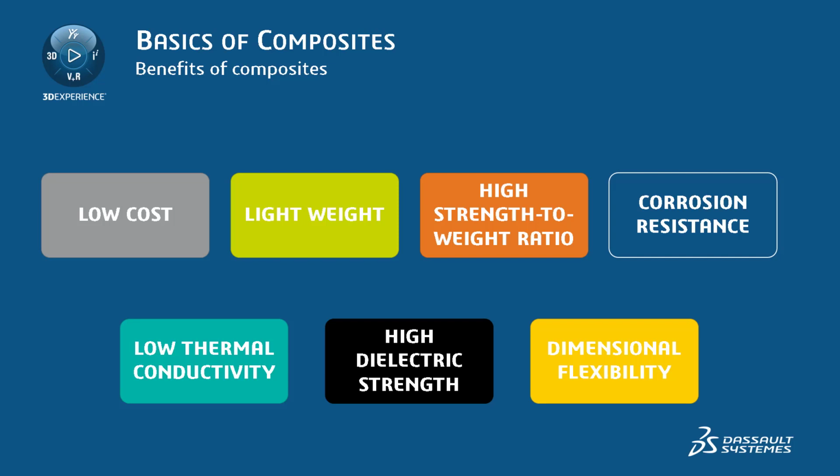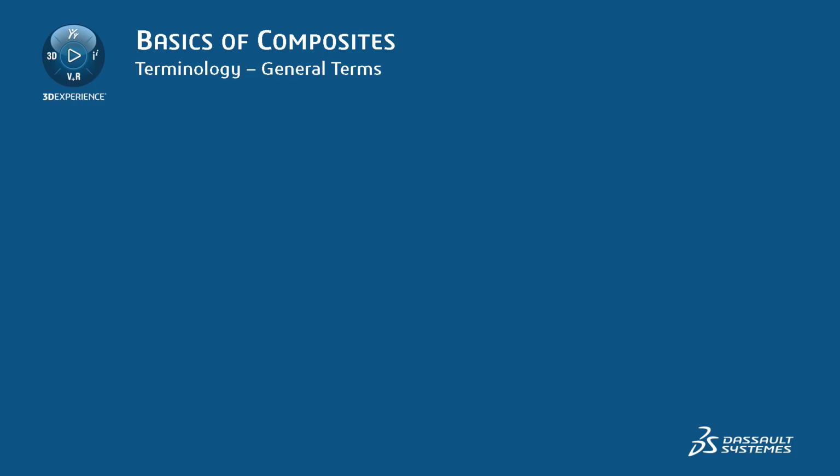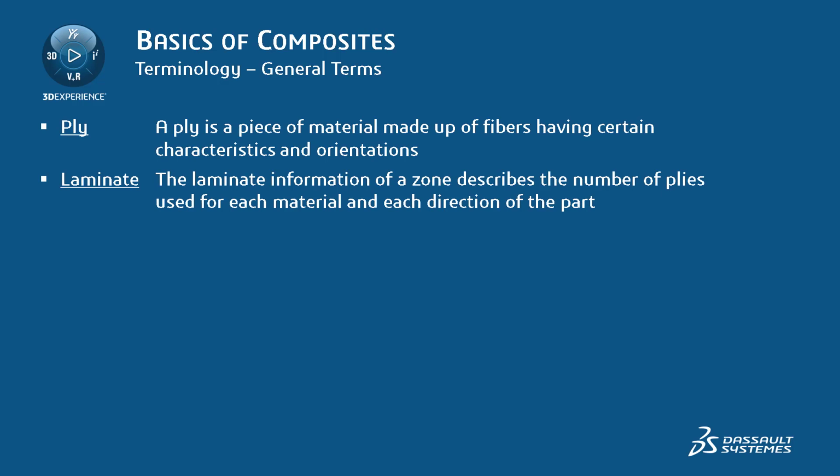Composites are more brittle than formed metals and thus are subject to direct permanent damage. Furthermore, repair introduces new handling constraints, like the fact that composite materials require refrigerated transport and storage, and have limited shelf lives.